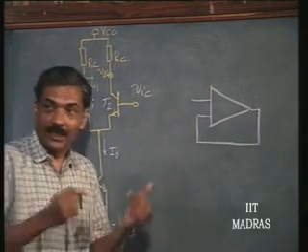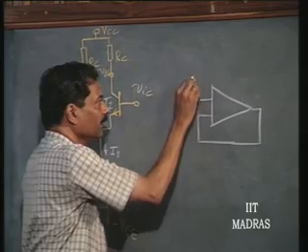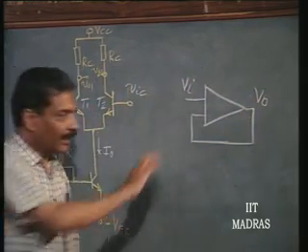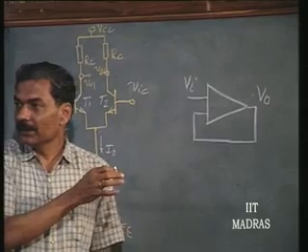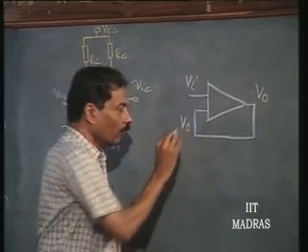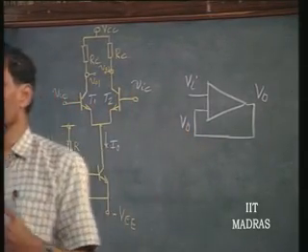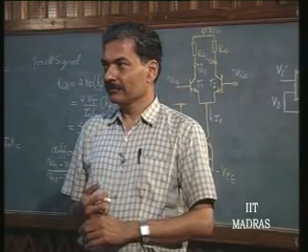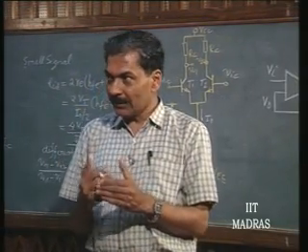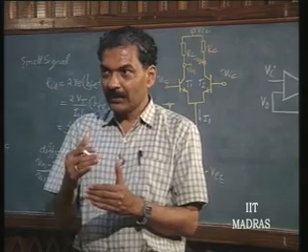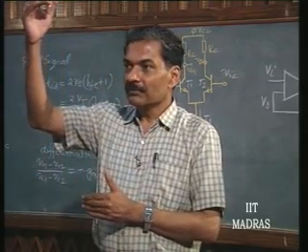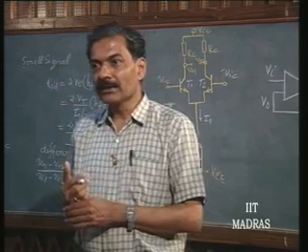The common mode signal situation: if this is Vi, this is going to be Vo, and the entire output voltage is fed back. So, what is the common mode voltage of a unity gain amplifier? Vi itself. And you would like Vi, when this is acting as a buffer stage, to go as much as VCC itself, in any practical situation.